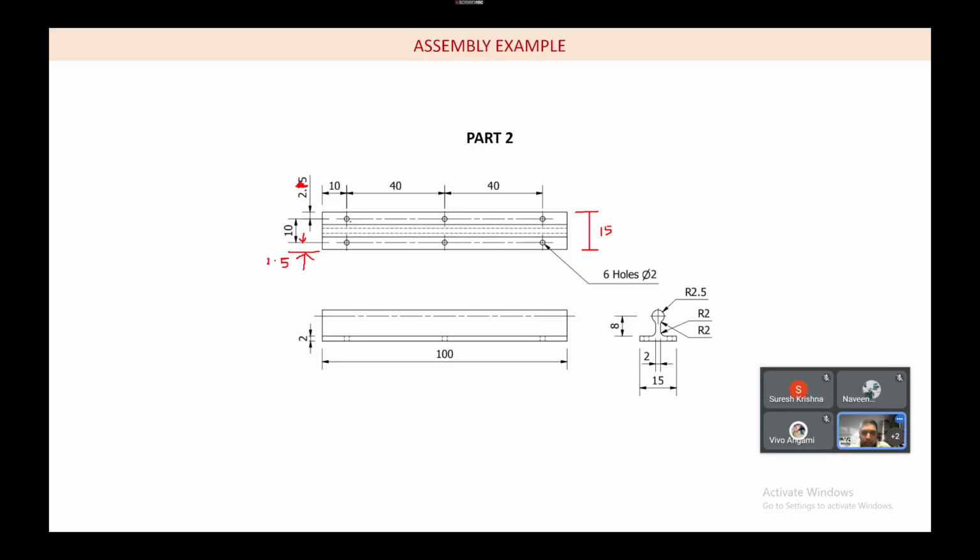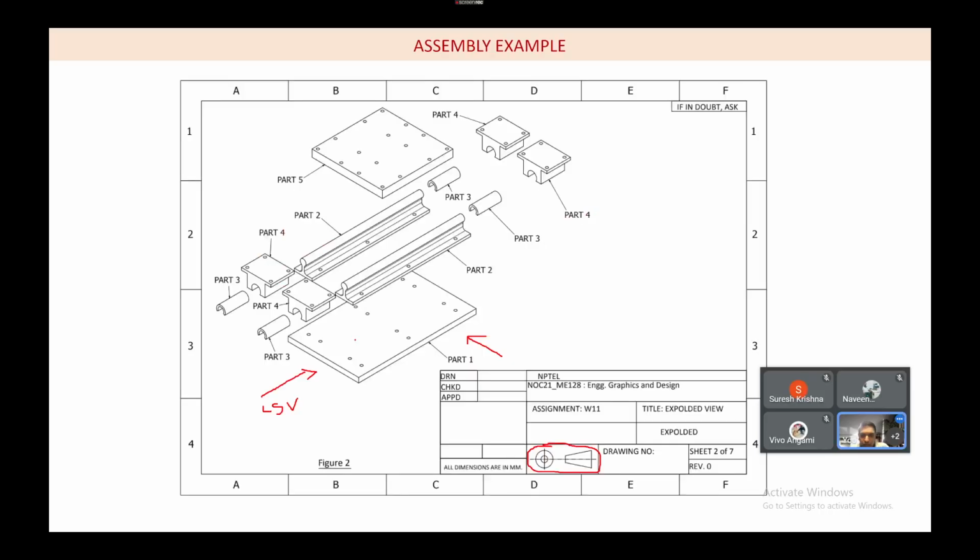So here if you see, this is a third angle projection, because the left side view comes towards the left hand side. So again we'll set the sketch to the left side. So which is this sketch. Yes.